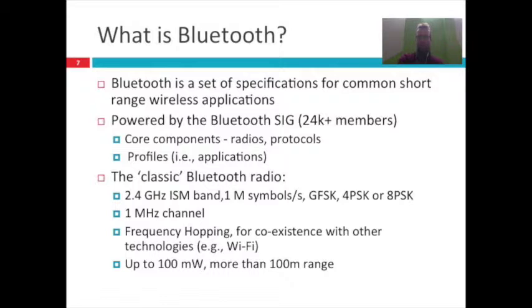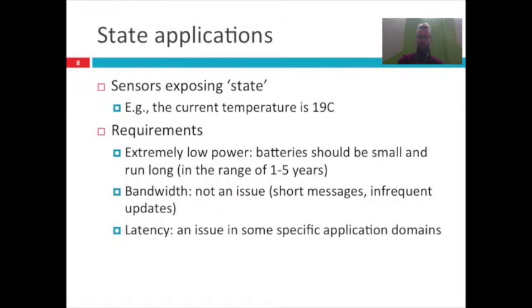It transmits in channels which are 1 megahertz wide, and it uses a technique called frequency hopping for coexistence with other technologies operating in the same band, like Wi-Fi. It transmits at up to 100 milliwatt of power, covering a range of more than 100 meters.